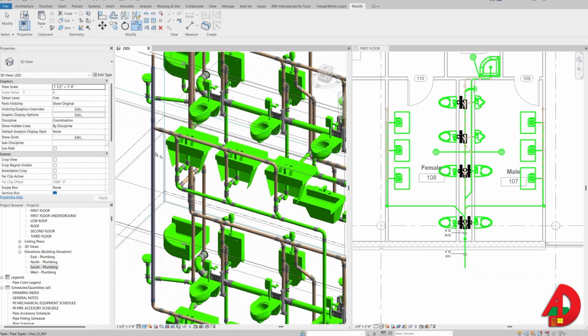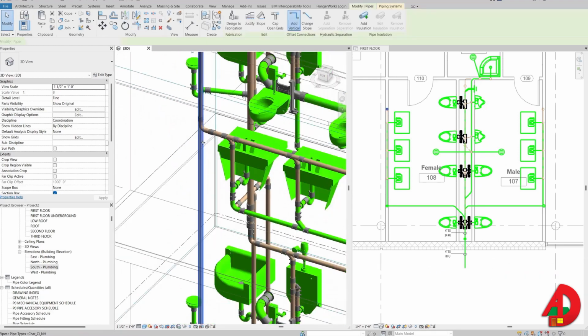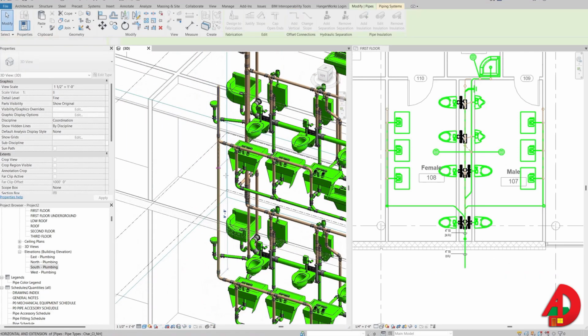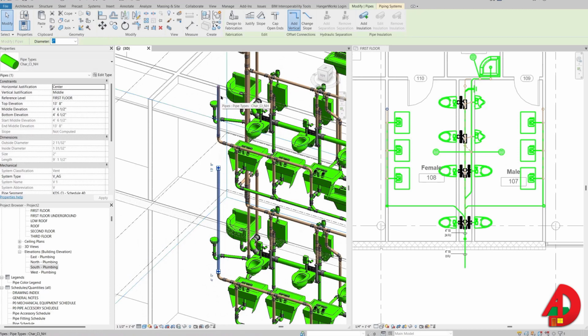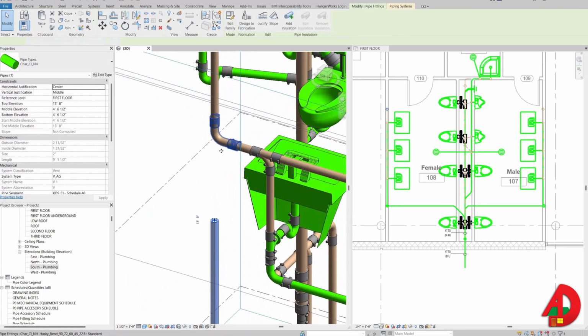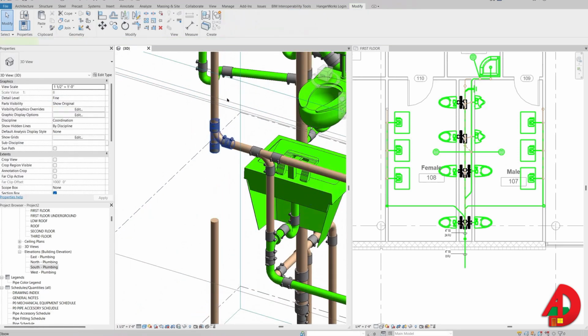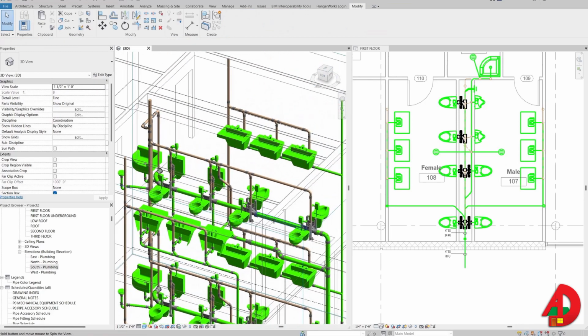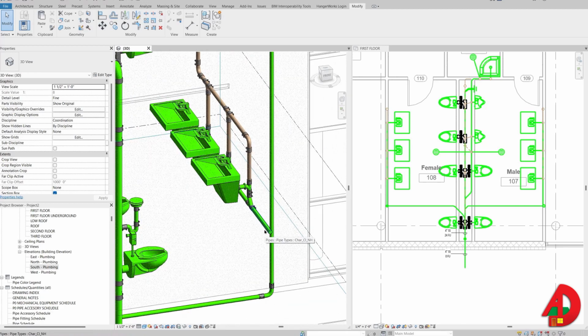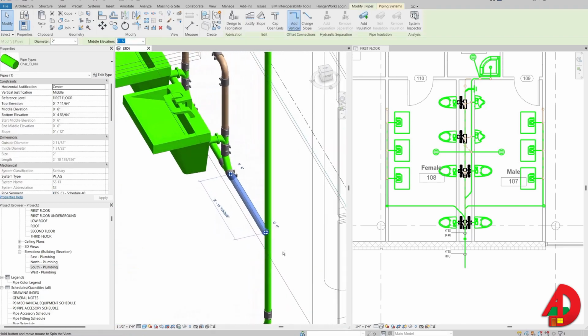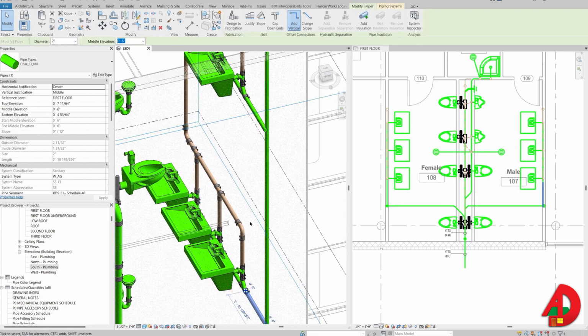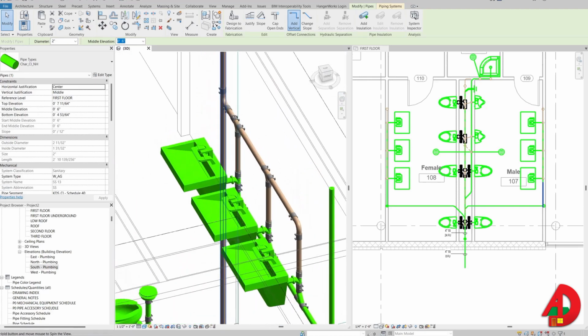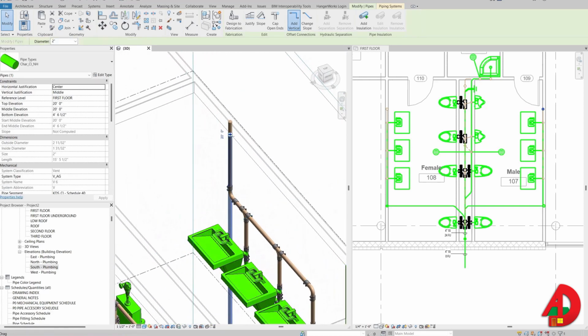Also, to connect the vent, I need to turn this vent into a T and then shorten this pipe segment, select the fitting and connect into the pipe. As for the other side, if I orbit around, I can see the pipes are not aligned. Before I go and align them, I will use the same procedure to connect the vent riser first.